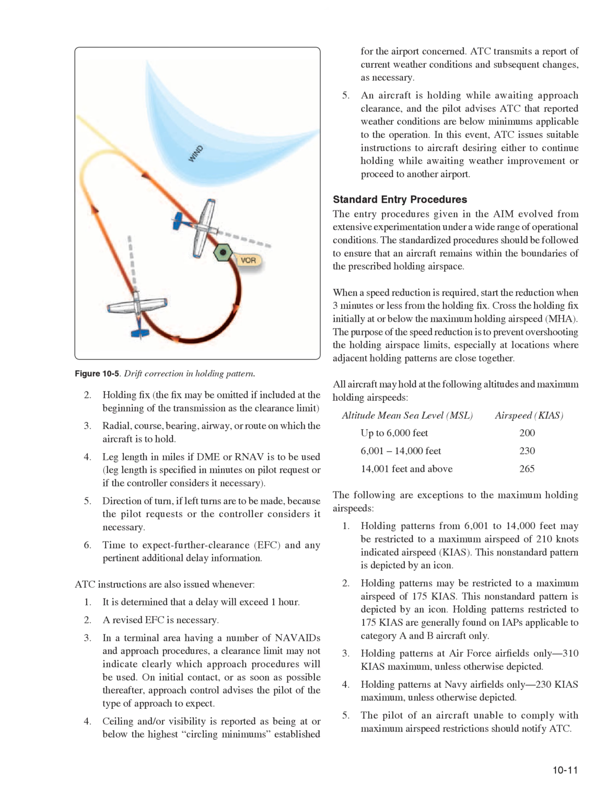ATC instructions are also issued whenever: 1. It is determined that a delay will exceed 1 hour. 2. A revised EFC is necessary. 3. In a terminal area having a number of navaids and approach procedures, a clearance limit may not indicate clearly which approach procedures will be used.